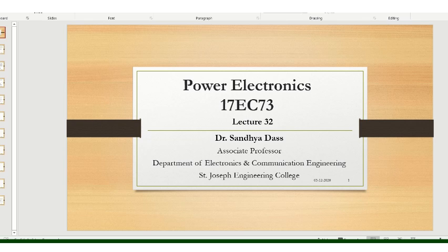So, these switching mode regulators are nothing but the DC to DC converters which are used as regulator circuits. As we know, in DC to DC converters we are controlling or varying the average DC level at the load to the desired level, whether we want the output to be higher than the input or lower than the input. In both cases, depending on the application or the demand of the load, the DC level will be either stepped up or stepped down.